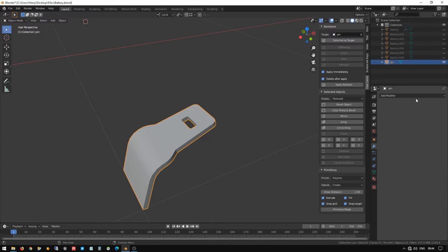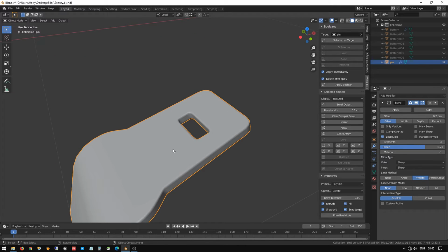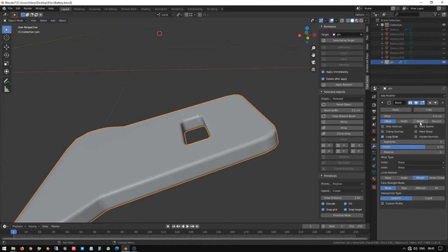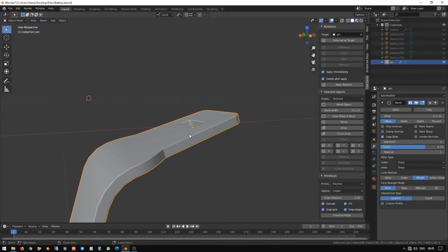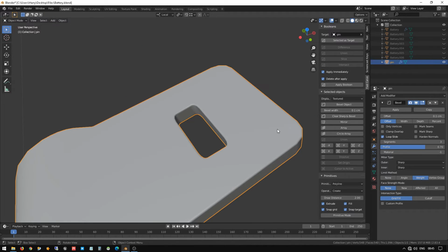So after creating this, you can press the object and bevel the object and make it 0.2, and after doing that, 0.2 also looks some crispy, so I make it 0.1, and I just press Control 2, sorry, Control 1, sorry, that also is not taken.